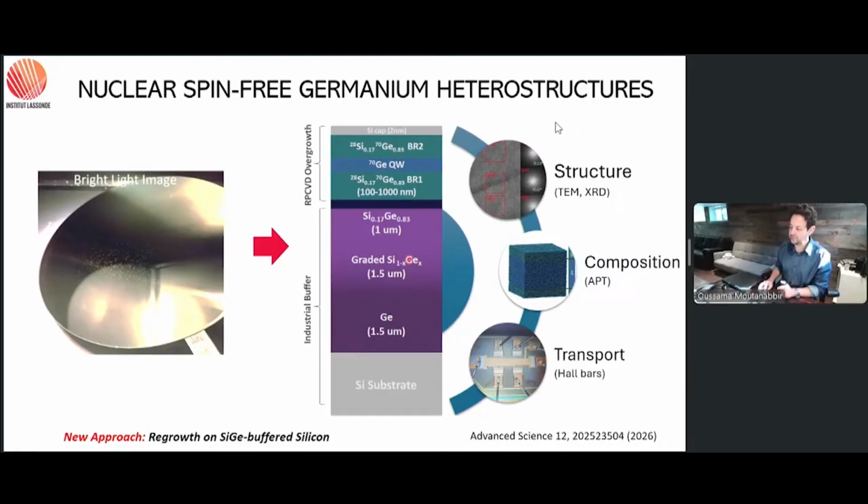But once you start with a silicon germanium wafer, we have two different oxides, silicon oxide and germanium oxide, and we spent, I'd say, more than a year and a half just to optimize the cleaning of silicon germanium wafers. It's a very tedious process, and whatever recipe you have, it's not the same if you change the stoichiometry. So if you are working with 20% silicon, the cleaning is different from 30%. The fraction of different oxides will play a role.